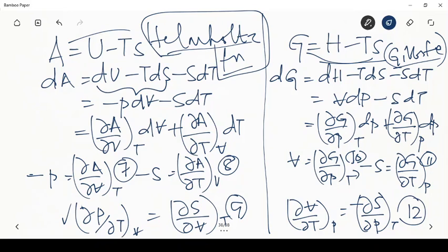So you can actually get values for entropy if we define a datum at which the entropy becomes 0, using these derivatives. The values of entropy can be evaluated, and if I can relate internal energy, enthalpy, Gibbs function, Helmholtz function to the entropy and temperature, pressure in some fashion, then we should be able to evaluate the other variables also. So these thermodynamic relationships come in very handy to construct property tables, calculating the quantities that are not directly measurable in terms of the quantities that are measurable. Right? So that is the purpose.